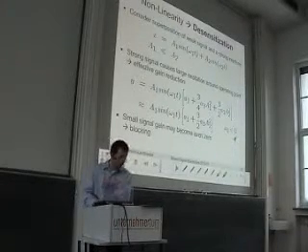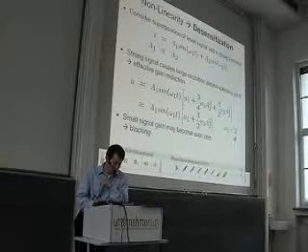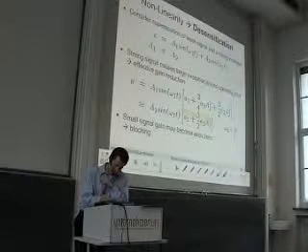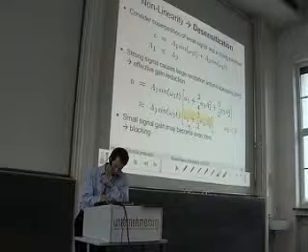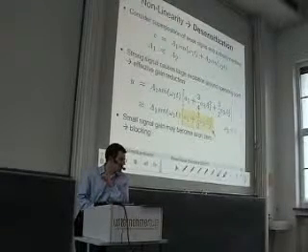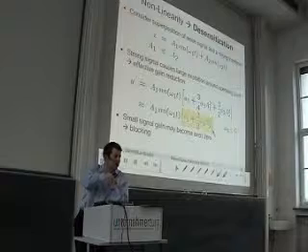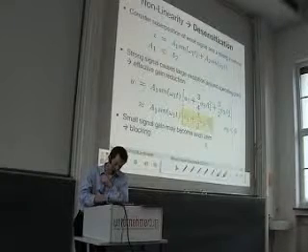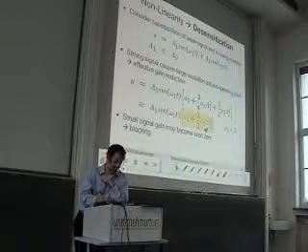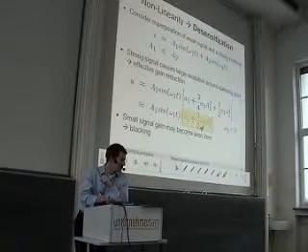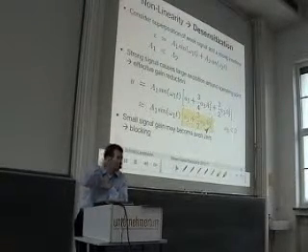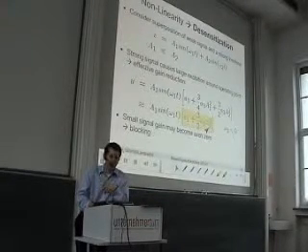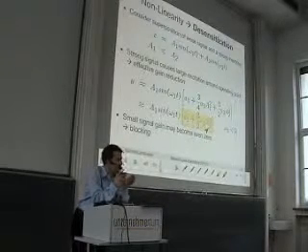But then what can we see from this equation? From this equation we can see that we have a gain term for the first fundamental, and this gain term sees a compression by the amplitude of the second signal. So if A2 goes up, and the small a3 is negative, then this A2 reduces the gain of the first signal.